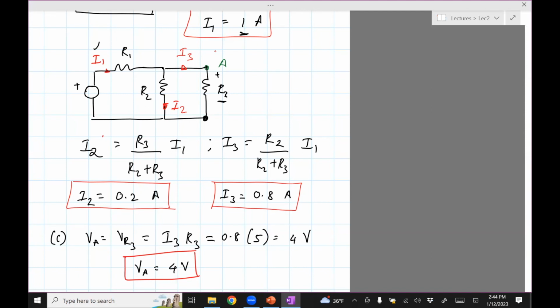Okay, so why is this important? That happens very often when you wire something. For example, a motor is not functioning, is not spinning fast enough. Then the next thing you do is compute the voltage which is supplied to the motor. You see that it is less than what you would expect. So between that and the power supply is probably a resistor which is drawing the current. And that's your starting step to debug the circuit.